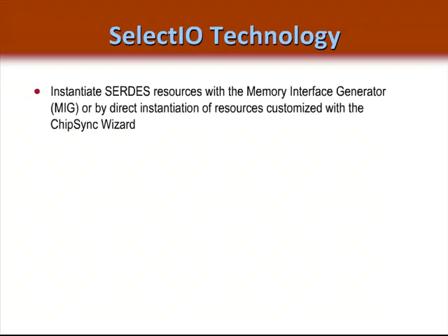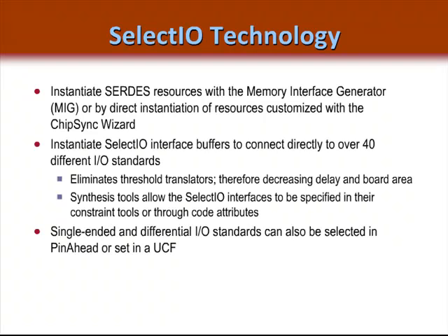The MIG, or Memory Interface Generator, and the ChipSync Wizard are used for this purpose. The MIG, of course, builds custom memory controllers, but if a designer only needs to customize the SERDES functionality, he can use the ChipSync Wizard. Besides the SERDES functionality, each I/O pin can be programmed to communicate with over 40 different I/O standards, including some differential I/O standards. This programmability improves performance significantly.